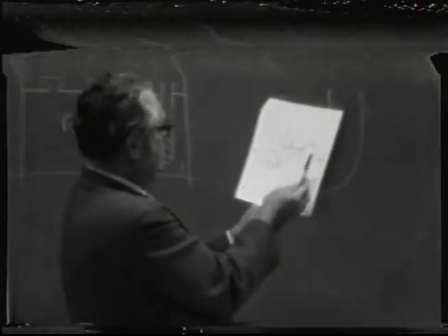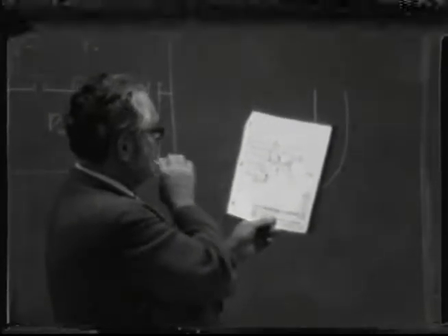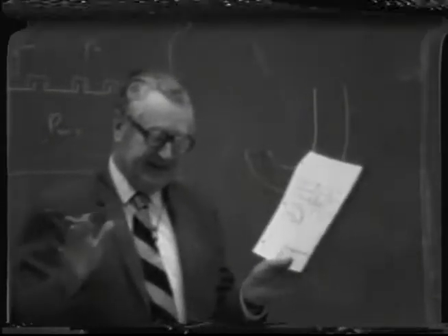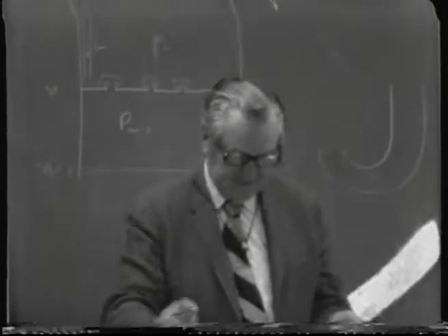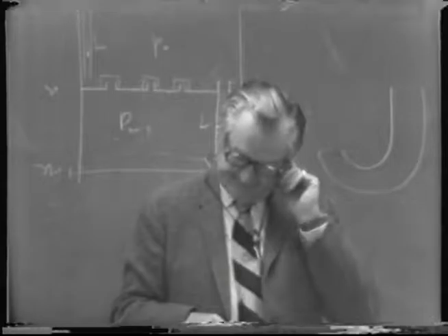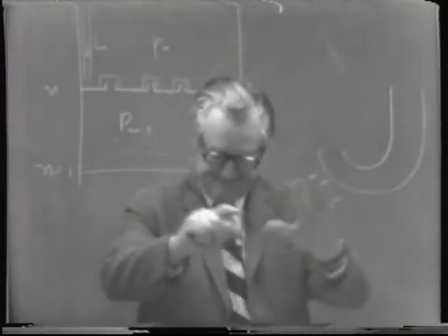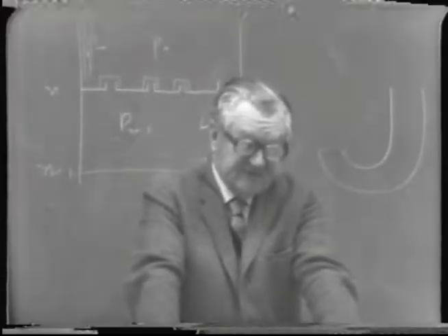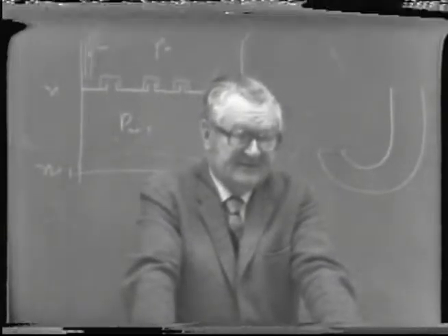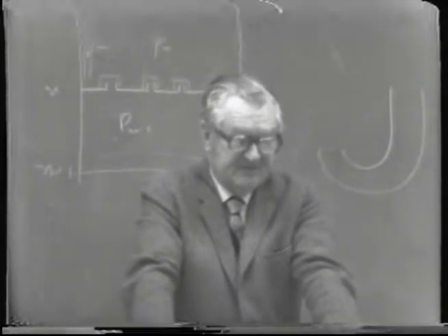So what is done here is this high pressure steam is allowed to expand through an orifice or a venturi type tube, where it gives up pressure energy and is converted into velocity energy.